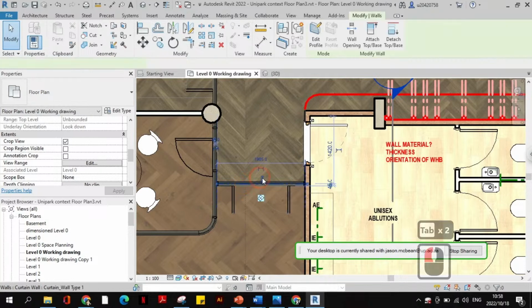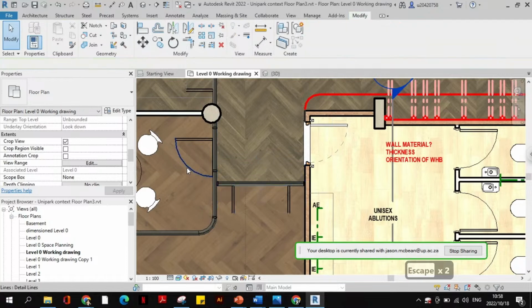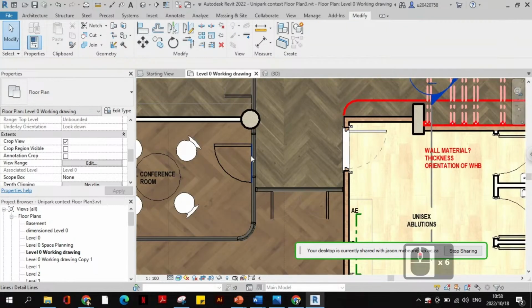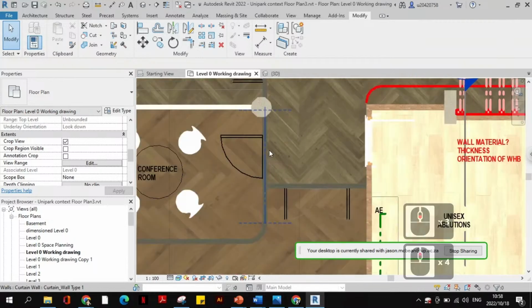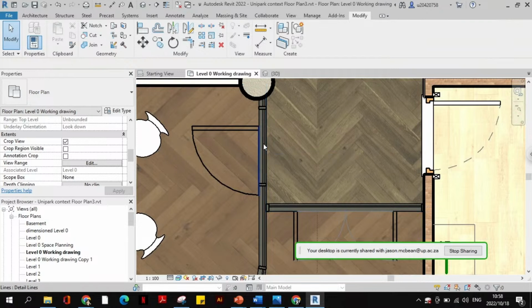So you want to put an arch door in there. Okay, what we'll do in this instance is you can use a glass wall. You actually make a wall that's glass, and you put the glass wall in, because this is a little tricky. Wondering if you just make the door a whole family rather, then you embed it and tell the shop fronts to stop to it. This is where it gets a bit strange. It gets weird. I might need it for one or two doors on the exterior.